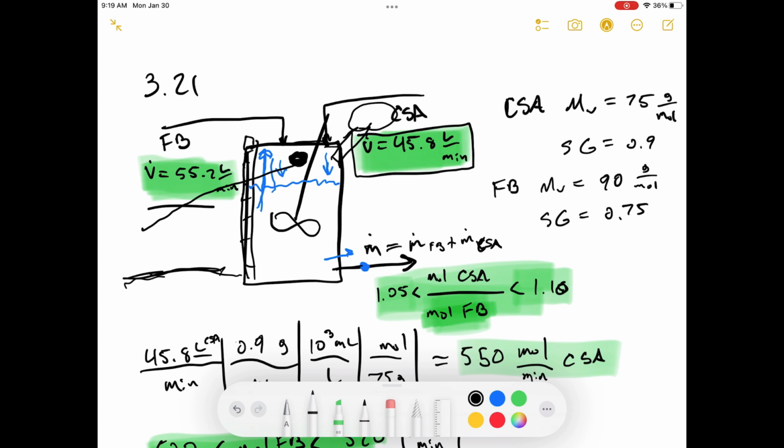So if you did have a gas in this space right here, you would start pressurizing this gas, and the pressure of that gas would build and build until you have so much pressure in there that either the tank fails or your pump fails, or something happens where you back something up in these inlet lines and something bad happens.